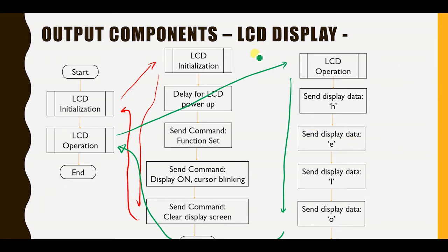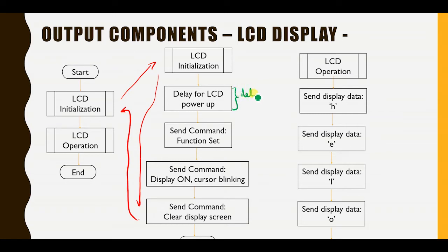So basically, in the LCD initialization, initialization is on power up, when you just turn on the LCD, and these are the things that you need to do. What are those? The first one, you need to provide a delay to power up. You need to give it some time to initialize itself, to run certain code inside itself, because the LCD itself has its own microcontroller.